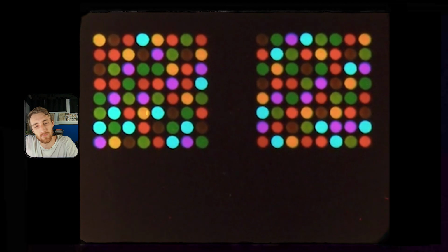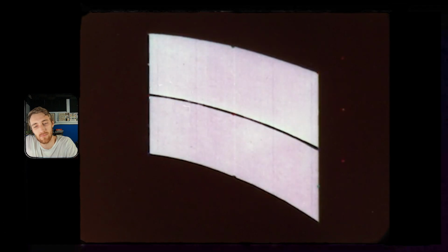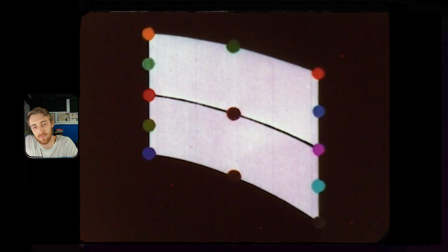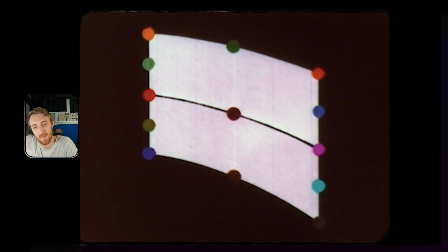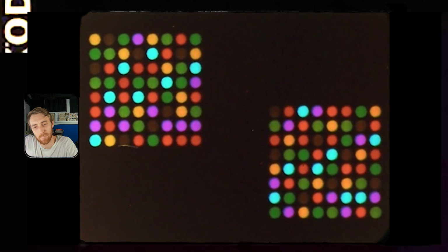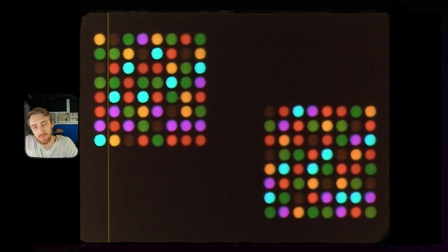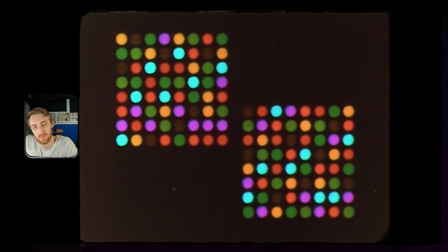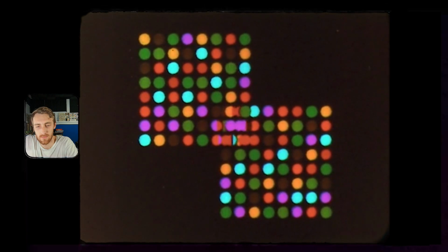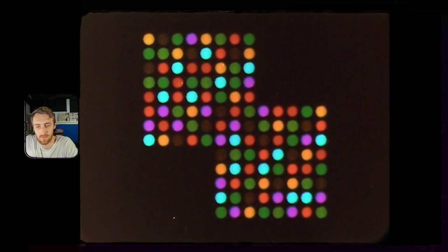Now, any two neighboring elements will have nodes in common. So values for common nodes will appear in both matrices. The matrices can therefore be combined by a simple merging technique. In practice, the process of solving the overall system equation is done concurrently with the combining of the matrices.